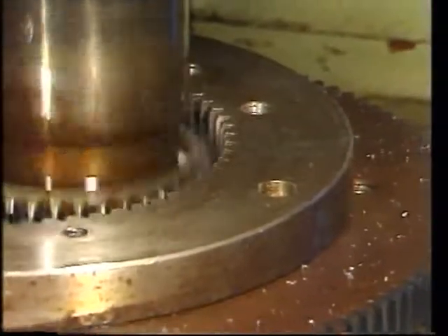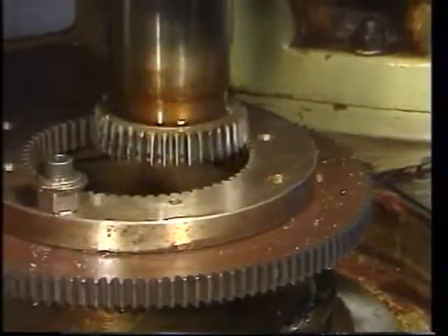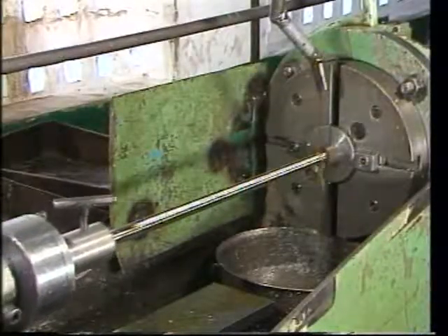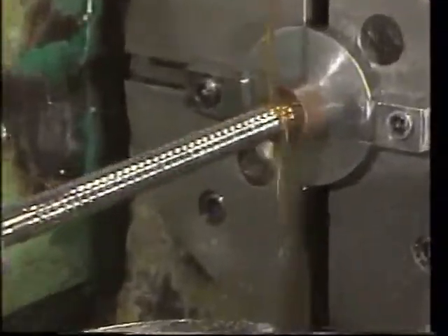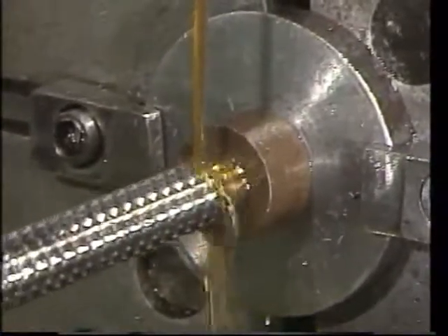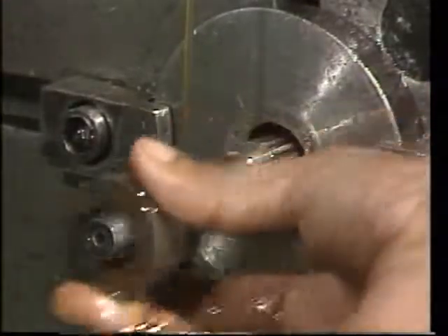Internal gears are produced for mass production by gear shaping using the pinion cutter. In case of large-scale production of internal gears in minimum time, broaching is preferred. A separate broach is required for every gear of different specifications.